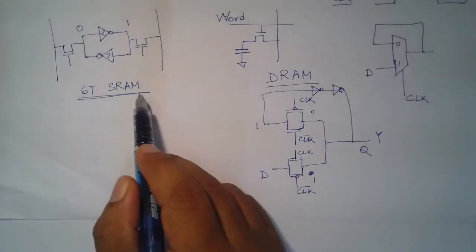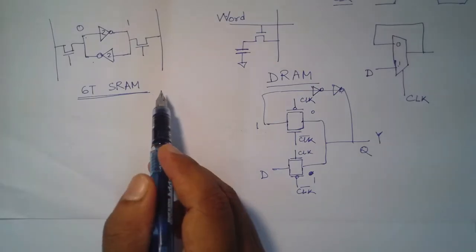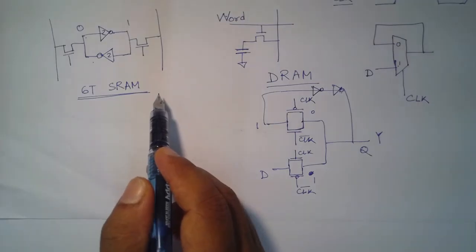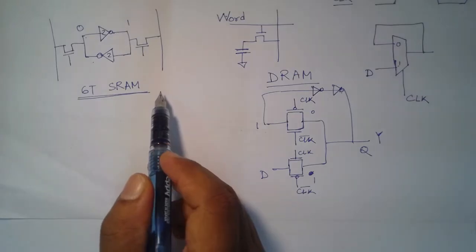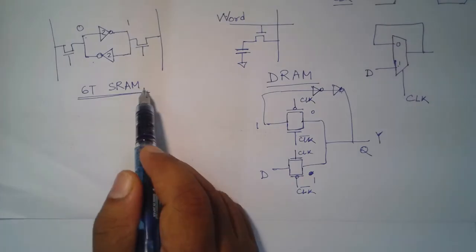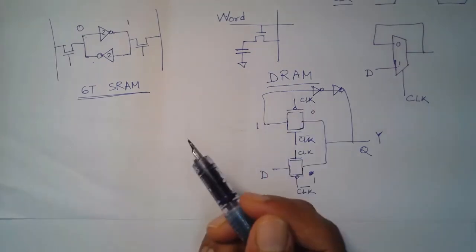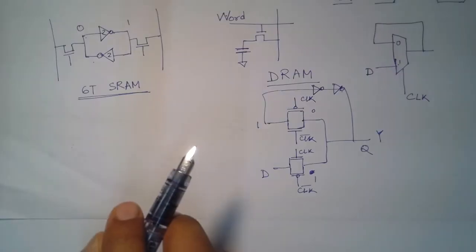So, this is a more intermediate solution, and it provides moderate speed which is very good, not as good as registers, but much better than DRAM, and the density is also better than registers, but of course not as good as the DRAM. So, these are the trade offs you need to be aware of in terms of different memory technologies which are available and their